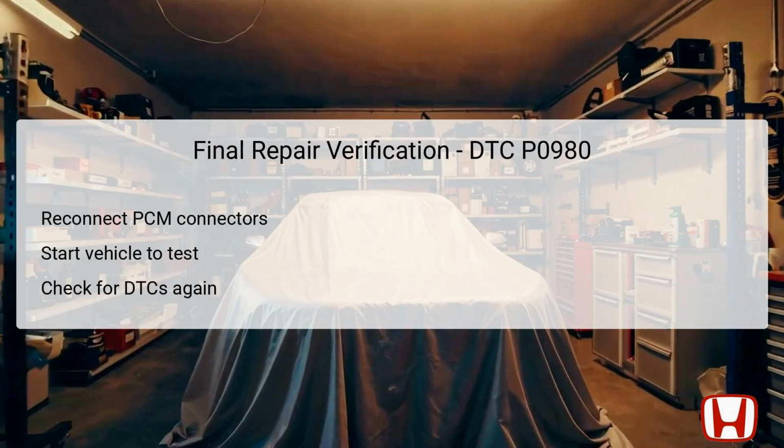After running the engine, it's necessary to check the HDS for any remaining DTCs. If DTC P0980 reappears, additional investigation is warranted, which may involve revisiting previous steps and double-checking connections and circuit integrity.